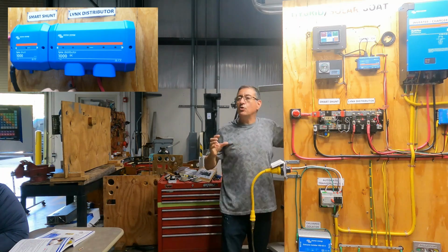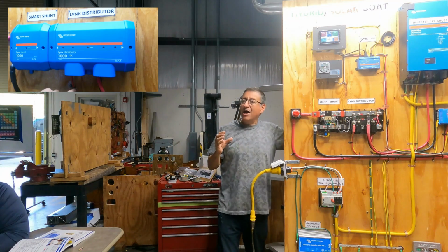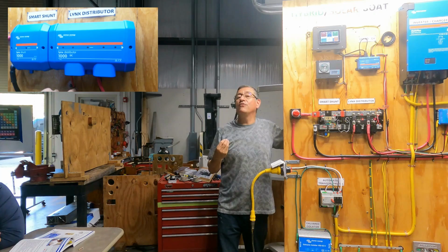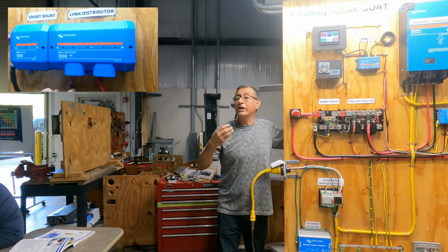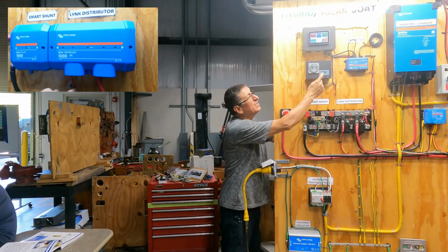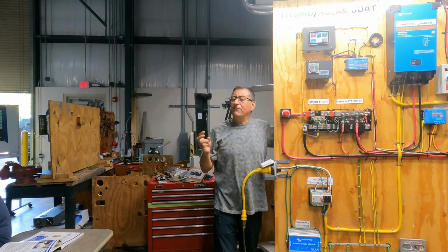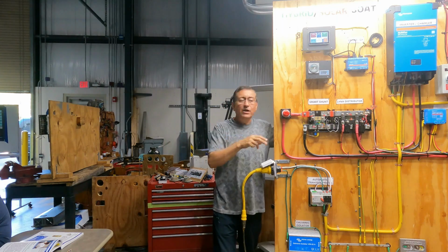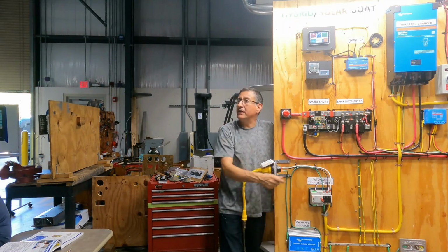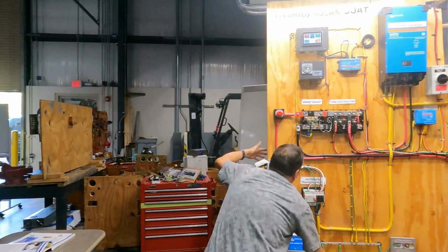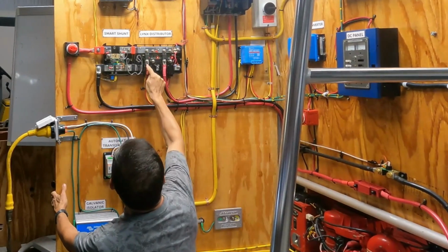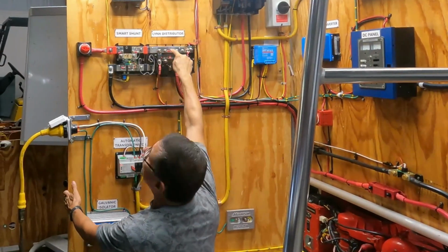In this system, you can administrate how much voltage and how many amps enter from the solar panel or from the charger, and how much voltage and amps DC are going out to the inverter. It's intelligent because you can administrate in those gauges the flow coming in and the flow coming out in the positive bus bar and negative bus bar. This is the DC side coming from the battery bank. Look at this. This is the negative bus bar, the yellow, and this is the positive bus bar connected with a mega fuse with the big positive bus bar.